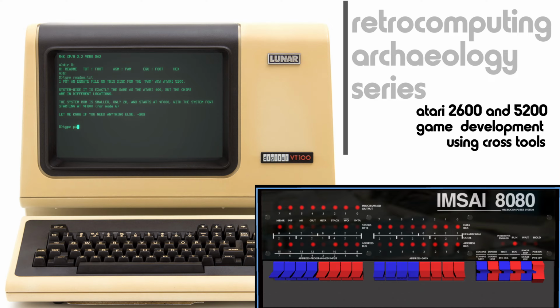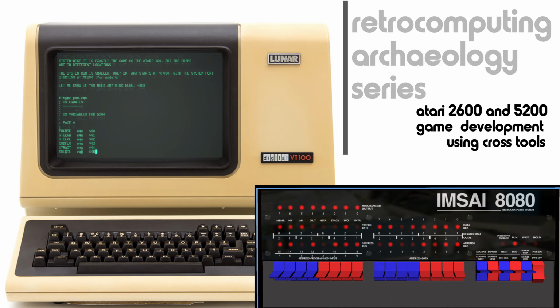So if we take a look a bit further, we can start to see more going on here. We can see equates for various system registers, for shadow registers, for interrupt vectors, and finally the different hardware registers for things like the GTIA, the ANTIC, the PIA, etc. All ready here and ready to be used. So what can we do with that? Well, let's see if we can at least do a basic little piece of software that we can use as a smoke test.